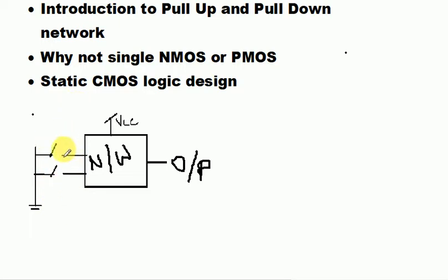That means when the switch is not connected to any other inputs, neither logic 0 nor logic 1, that is ground and VCC respectively. So there may be cases where this switch may take logic 0 or logic 1 or any value in between, and the output happens accordingly.